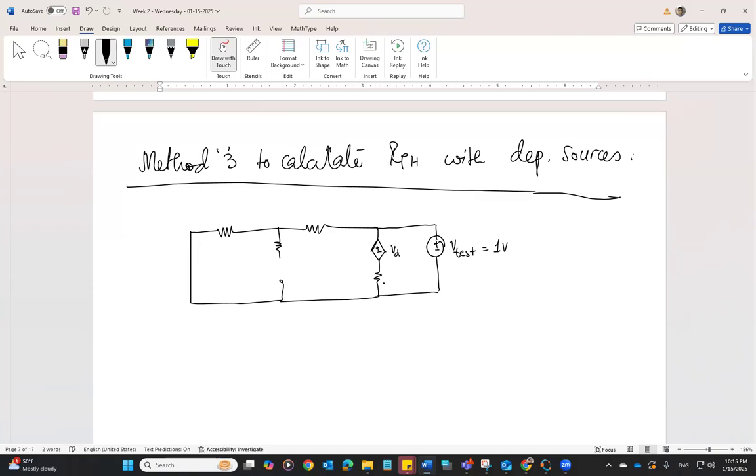This is VD, R4, R3, R1. And observe, since this is R2, but since this is open circuit, current is not going to flow through R2. So you can pretty much eliminate that branch if you want. We are trying to figure out this current coming out of the source, I test. How much is this current?